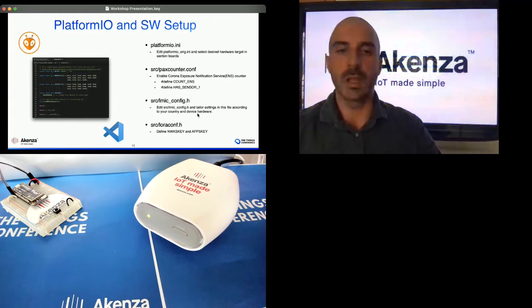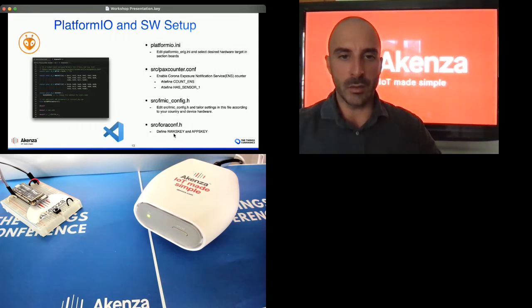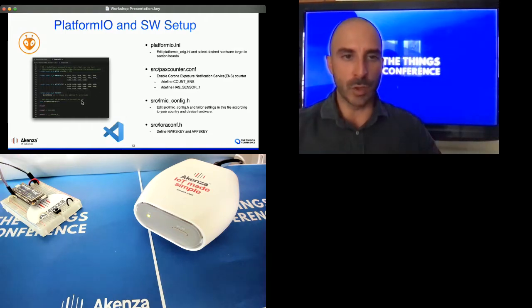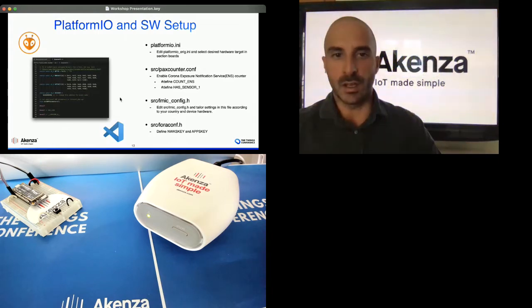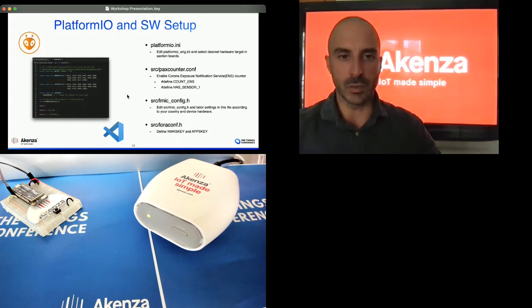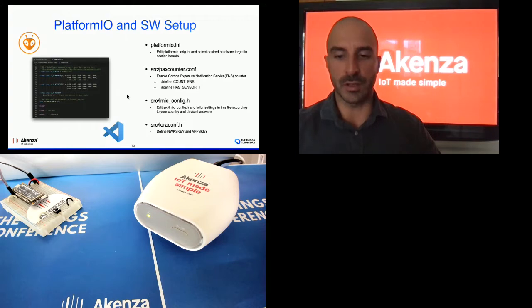It is easily standard, and in the loraconf.h we have defined the NWKSKEY and the APPSKEY, and it is very small, but it's visible here that we have just randomly set it up. And well, that's it. We have just reproduced it in our application in order to connect it to the application and to transmit the data.